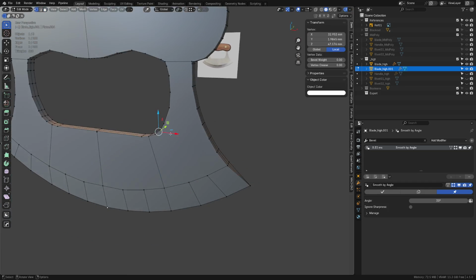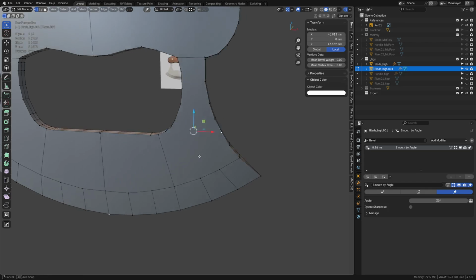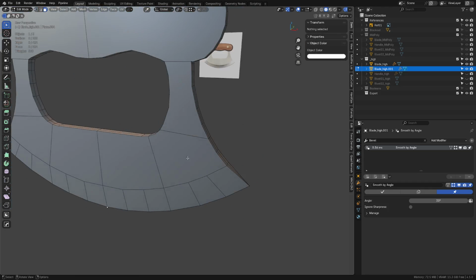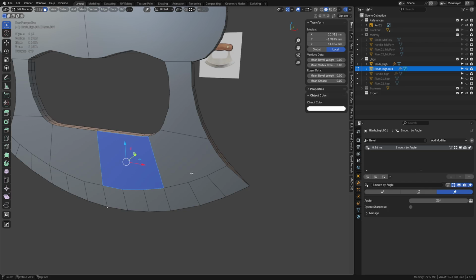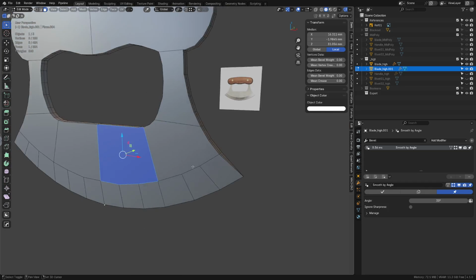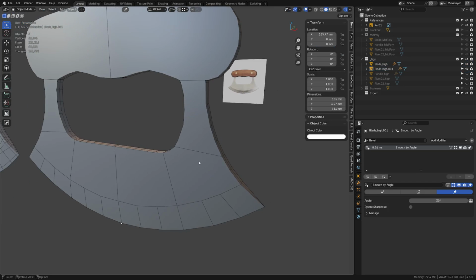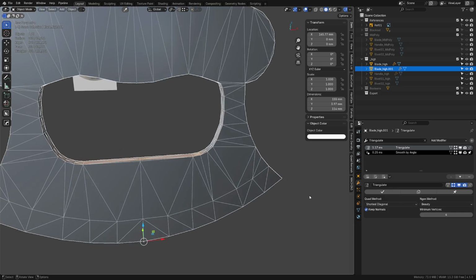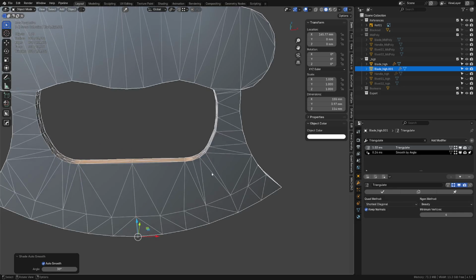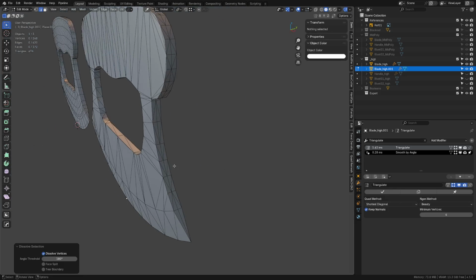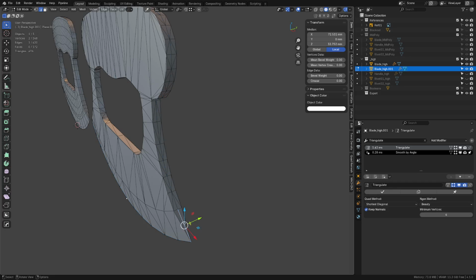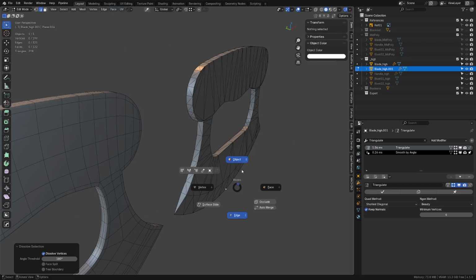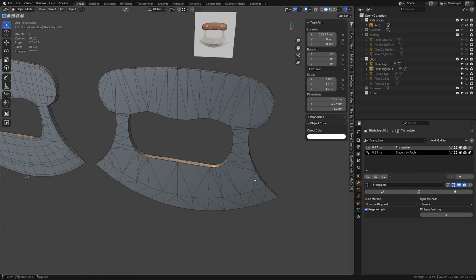As long as it's split up kind of evenly like you're doing quads still, right? These will be non-planar faces technically, but they're not too noticeable anyways, right? So later on, this gets triangulated. Keep normals, shade auto smooth, even weighted if you need to, but you can see how this can work out anyways. We can get a really nice optimal mesh out of it. Something like that for now.